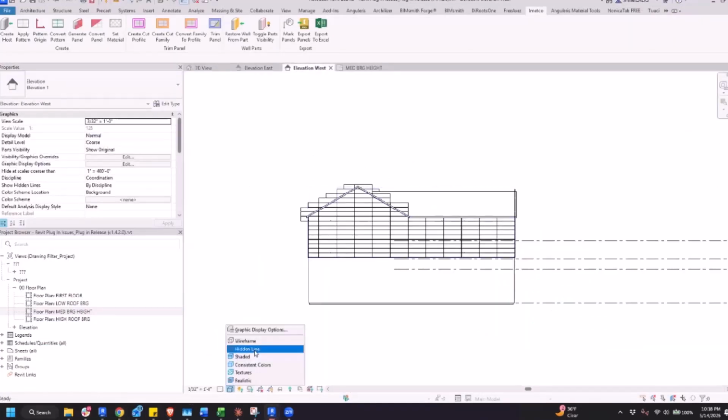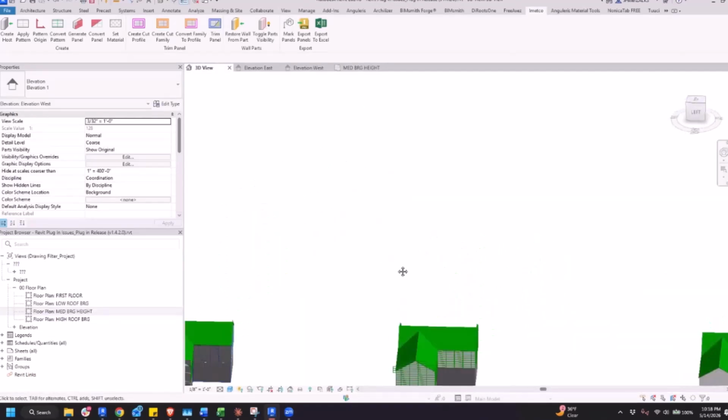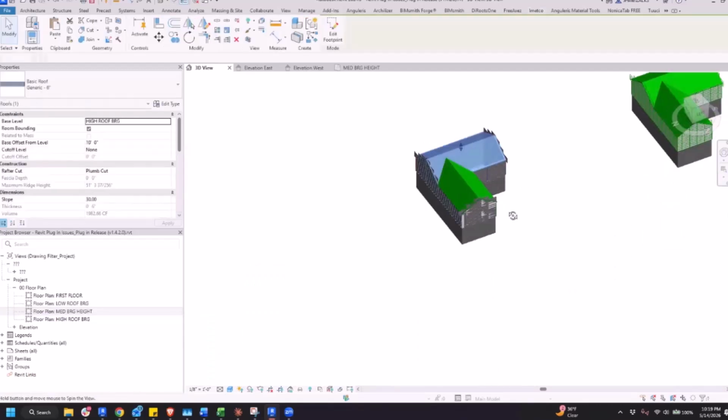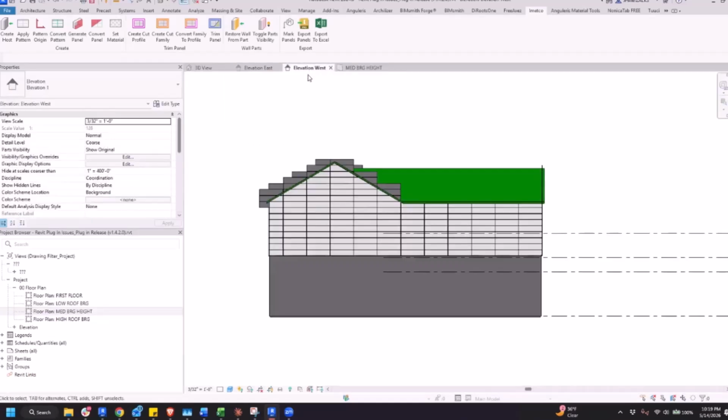So now that we have this shape right here, we can go to our tool once again, go to the create cut family, and once again you have to click on your wall because that way it knows where to host the void. Then you have to select all of your lines, which are going to be your entire void. Once you do that, it's going to run the family, import it, mold it to your shape, and place it in the right position. Right. Okay. And then you can see that it actually cut everything here.